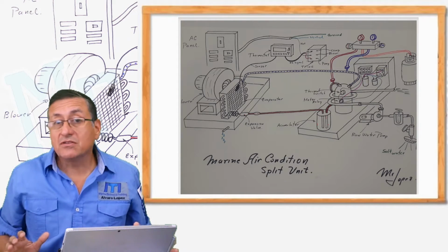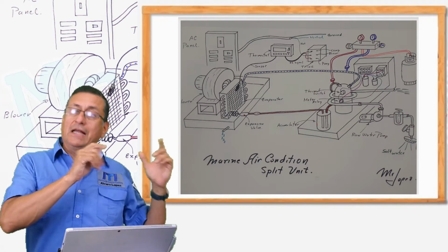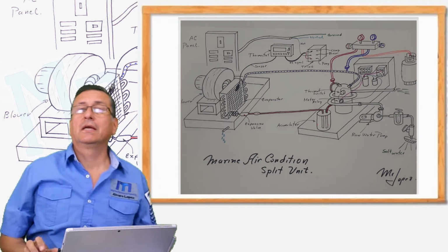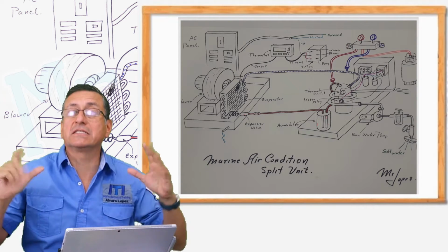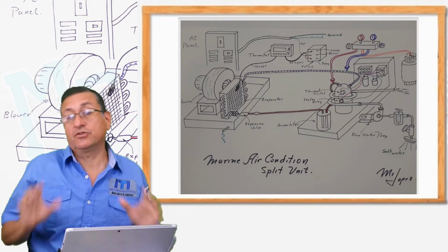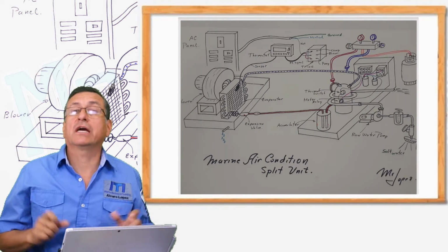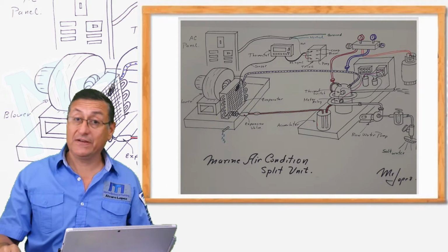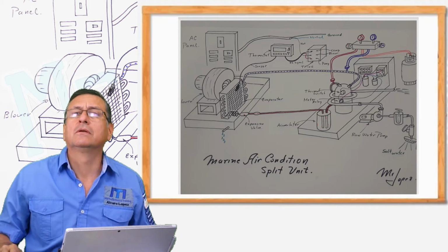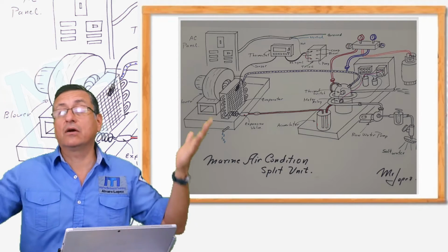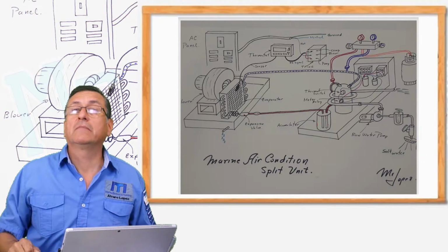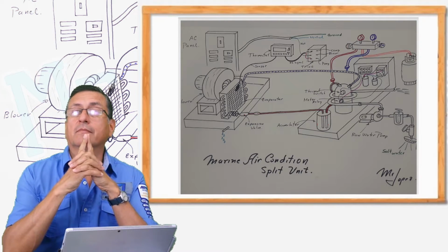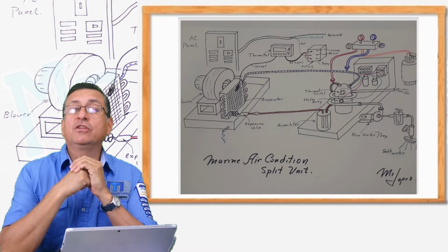Depending on the distance between the evaporator and the condenser, I have a lot of copper pipes, and we have a lot of chances for leaks, because it's possible that another contractor installing other equipment perforates that line and releases the refrigerant. It's very common in marine applications that other contractors installing other types of equipment make a drill and perforate those lines. That's not good. That's the inconvenience of the split unit.